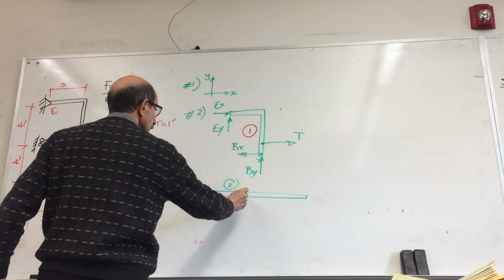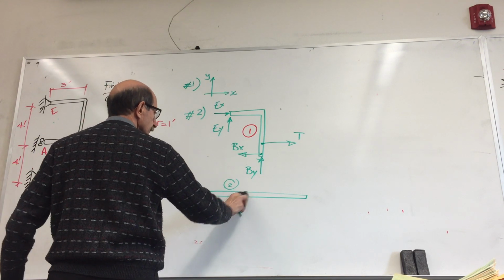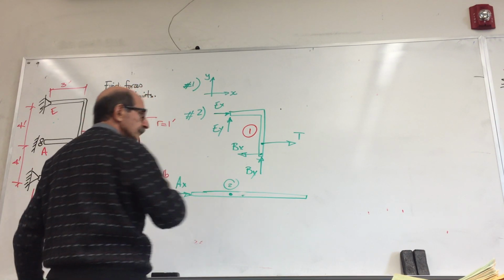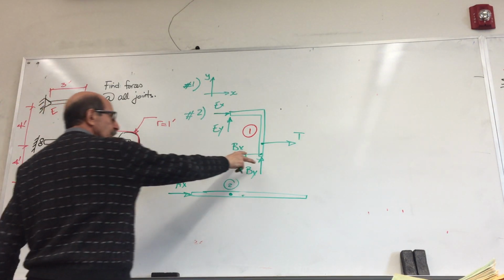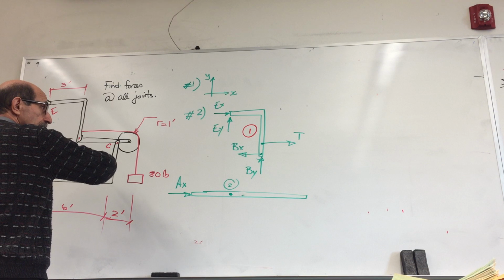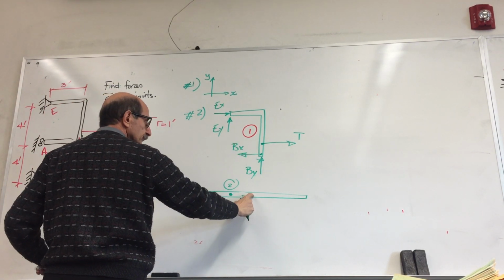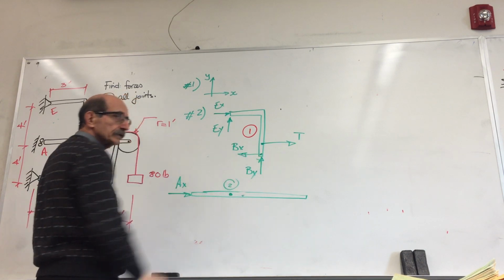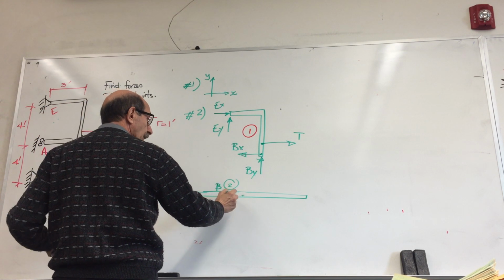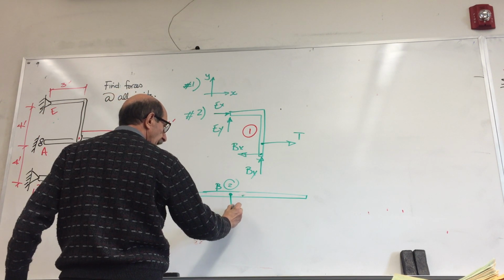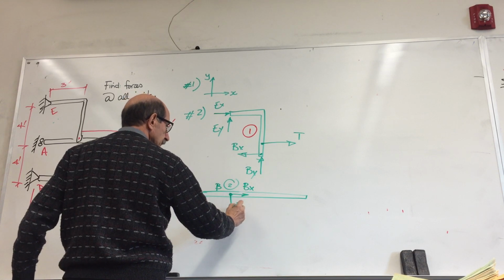At point B, which is here, slightly here, remember the law of action and reaction. If you assume these are the forces at this point, internal, that act on this member, these are the forces coming from that member acting on that one. So at this point, B, on this member, forces have to be equal in magnitude and opposite in direction.